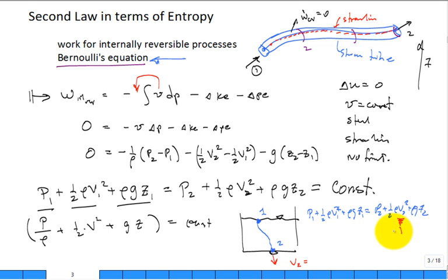Okay, well, tell me a little bit about the pressure at 1. If it's air above the water tank, what's the pressure at 1? Atmospheric pressure. What's the pressure at 2, the air under the tank? Atmospheric pressure. What's the pressure of the fluid issuing out of the hole at the bottom of the tank? It's atmospheric pressure. So guess what? These two pressures are the same. They cancel. I have a large diameter tank. It's slowly draining. What's the velocity of the fluid particle at 1? Negligible.